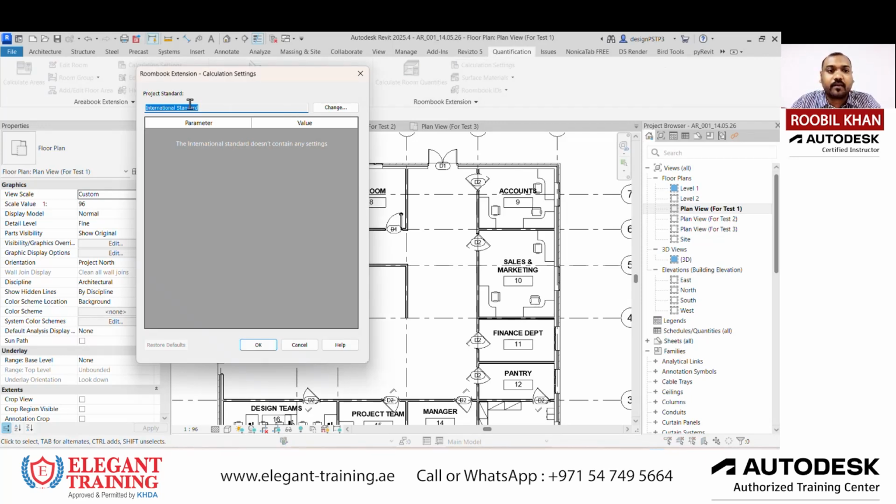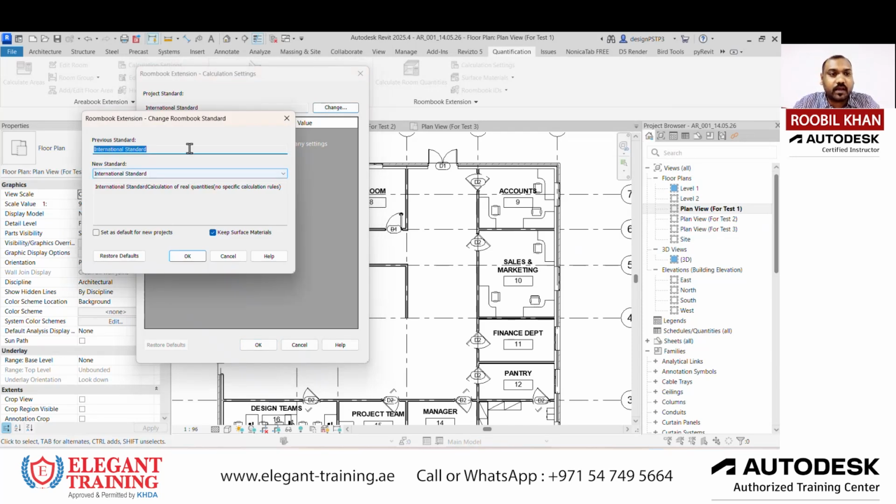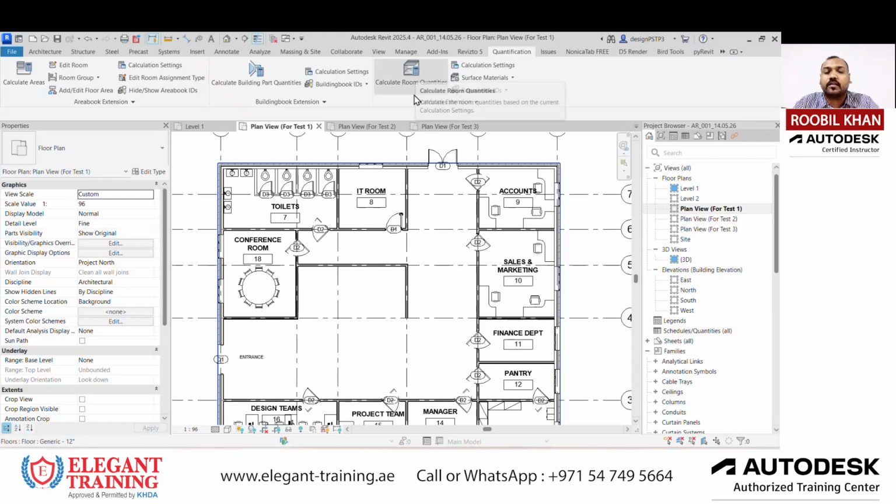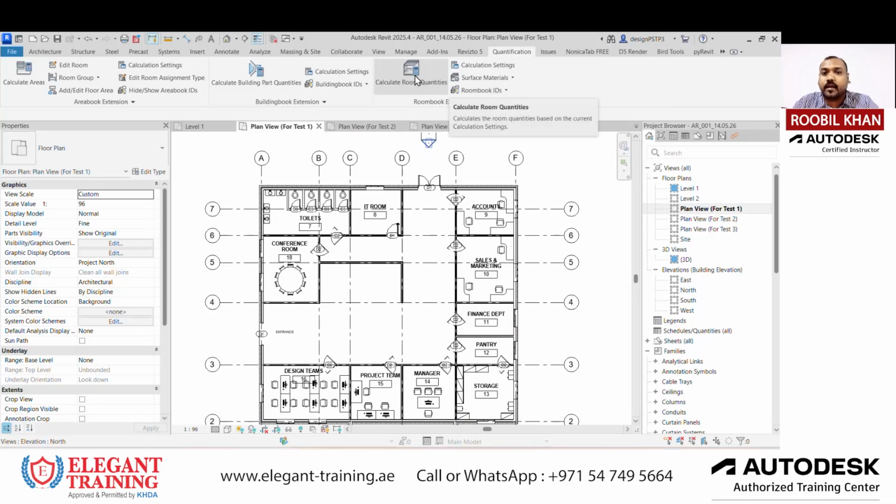From here you can go to the calculation settings. Here we are following the international standard. If you want to change to any other country's standards, you can also follow that. We are just following the international standard here, and from here I can go directly to Calculate Room Quantities. The first thing you need in Revit is the rooms. You need to annotate the rooms, or place analytical rooms over the plans. Then you can go to Calculate Room Quantities.